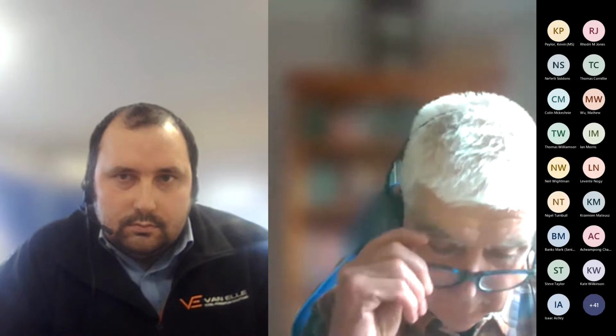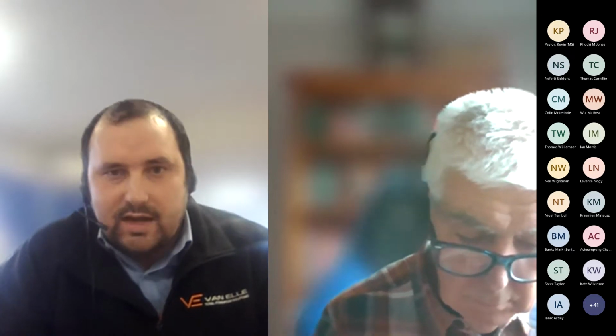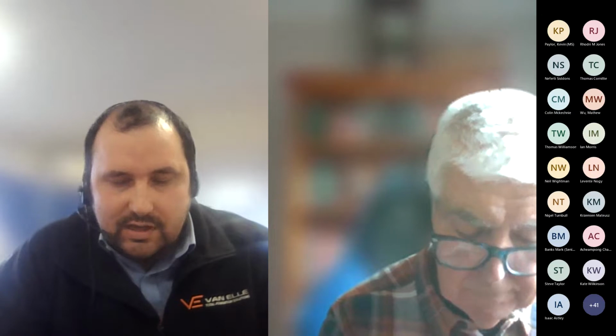And then the final one, looking into the future. We do the pile installation, we put what we consider to be reasonable tolerances, but then there's a future renewal of that track for whatever reason. What is the risk of your sleeper ending up underneath one of the piles and then creating a direct contact situation? Because it just feels like that's one of those things we wouldn't be able to control. How do we mitigate against that? Yeah, we've modelled that previously. Obviously, with the pile head being set down below the bottom ballast layer, it has a minimal impact on where the actual sleeper is relative to it.